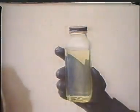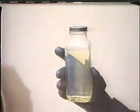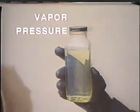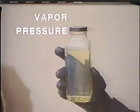The vapor pressure of the reformate product must also be controlled during the reforming process. Vapor pressure is a measure of a liquid's tendency to vaporize at a given temperature. Light hydrocarbons, like propane, have a high vapor pressure because they vaporize readily at normal temperatures. We usually try to keep the vapor pressure of the reformate low enough so that it will stay in a liquid state under average climatic conditions.